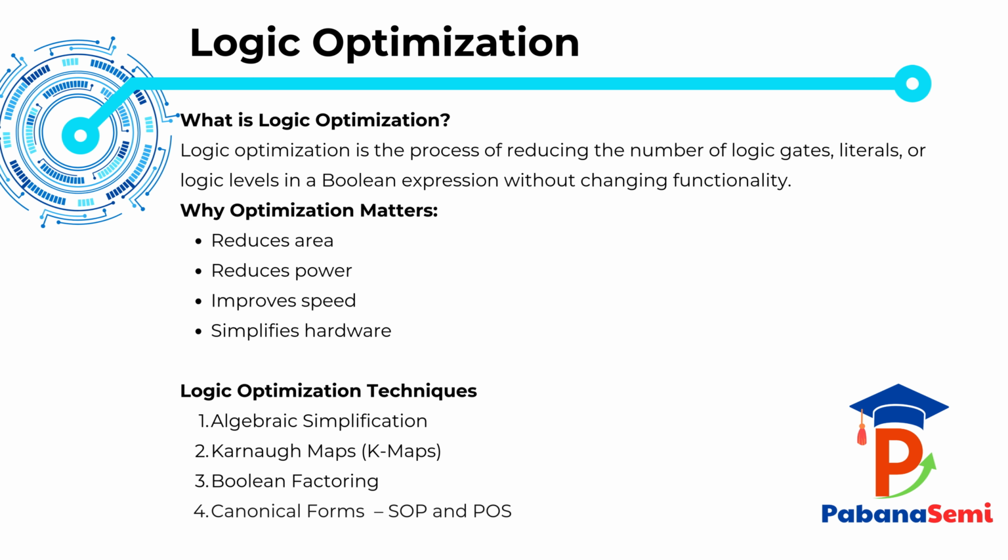Now let's delve into the fascinating realm of logic optimization, an exceptionally significant concept in the domain of digital design. Logic optimization is the intricate process of minimizing the number of logic gates, literals, or logic levels within a Boolean expression, all without altering its functionality. In simpler terms, we aim to make the logic smaller, faster, and much more efficient, while ensuring that the output remains absolutely unchanged.